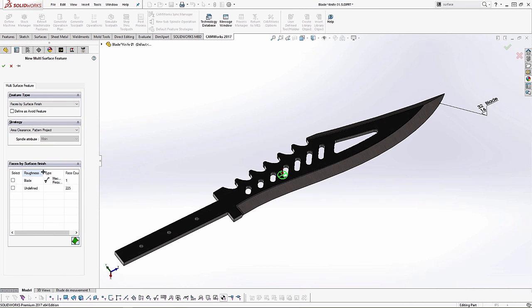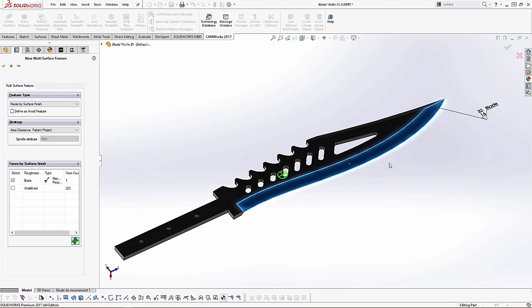So when I select that, I get a list here of all of the different surface finishes I have in my part. I simply select which one I'm hoping to create a feature out of. So if we're doing mold machining, where you might have several different surface finishes throughout the part, all called out in the 3D model, this would be a very quick and accurate way of ensuring that whatever strategy we're using to cut each part is tied directly to the surface finish.